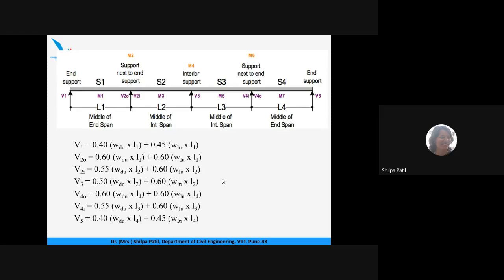In this fashion, the planning and designing is done so that the practical implementation also becomes easy and on the same side economical. If you go on changing the dimensions in every room for beam and slab, then the formwork required will also be large. Obviously that will cost money, because for every room you have to provide different formwork, different centering, everything will cost higher and higher money. Is it clear how these moments and shear forces are calculated by making use of empirical method?